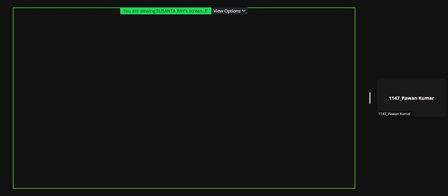I think up to the number of conductors per slot and all these things we have finalized in the last class itself. So today, did we calculate the cross-sectional area of the conductors taking current into consideration? No, sir. Then you start that. First you find out the phase current.